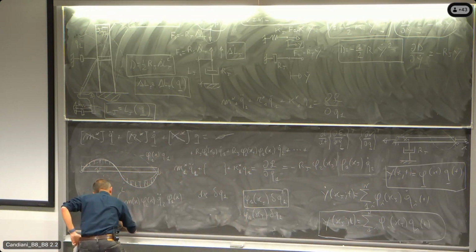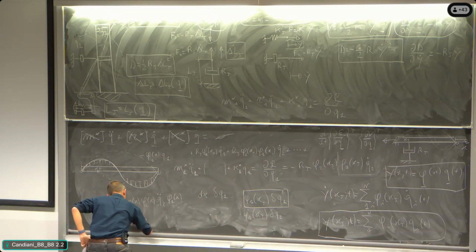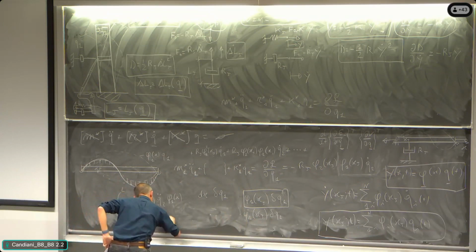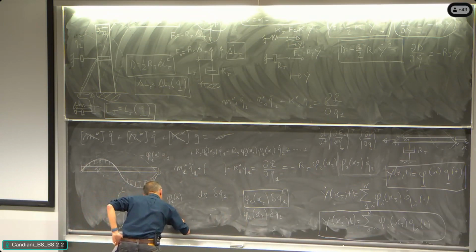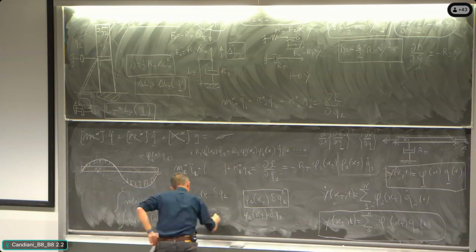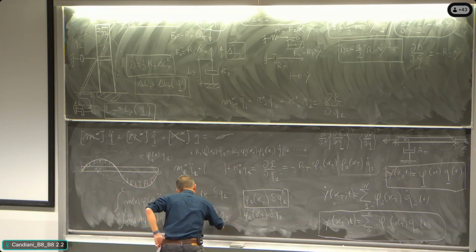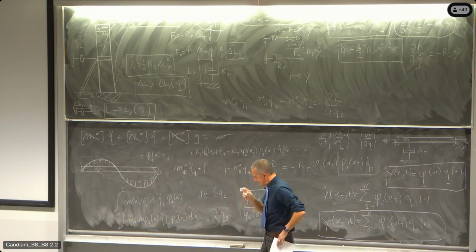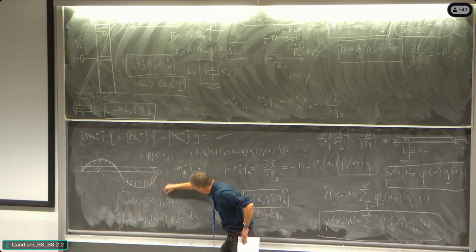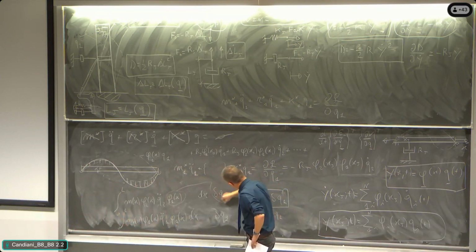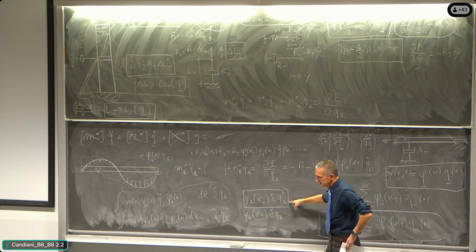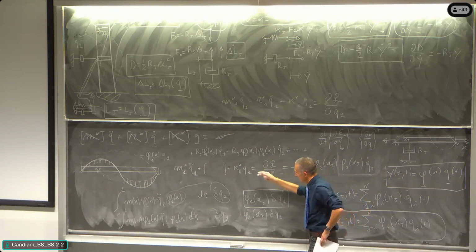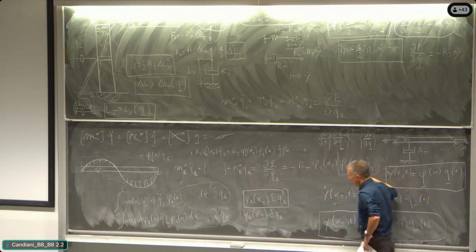So integral 0 to L of m function of x, phi1 function of x, q1 two dots, and then phi1 function of x delta q1, and here dx. So I pretend that you understand that phi1 delta q1 is the virtual displacement associated to the virtual movement of the first coordinate. I want to write the first equation.